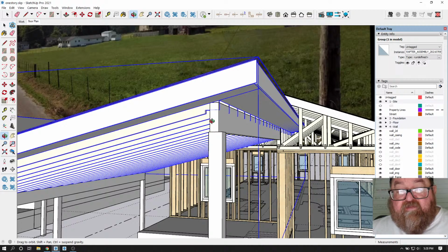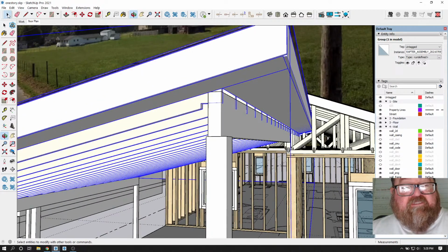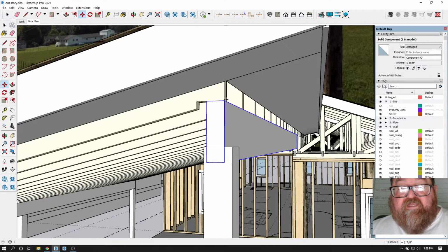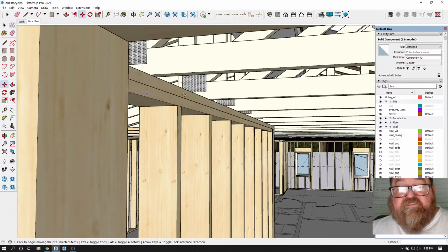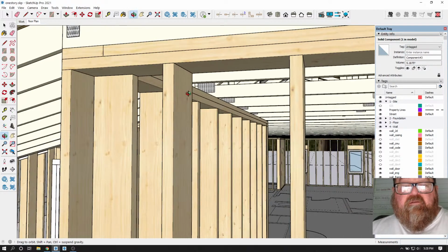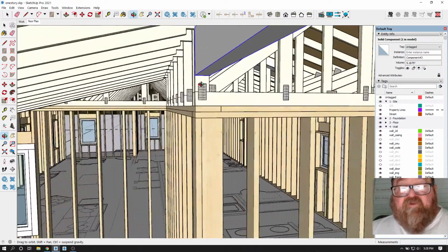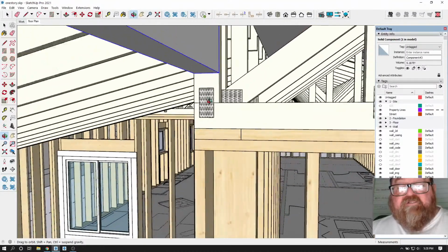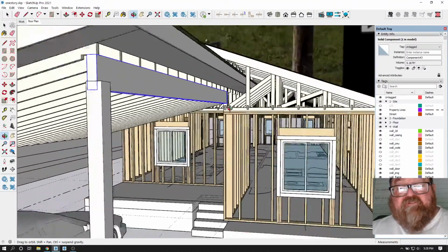What I'm trying to do is get this beam right. If there's going to be a bird's mouth, it would really be right here, and then this would be whatever the beam. If this is framing and that's all lined up, that is correct, if this was 2 LVLs.